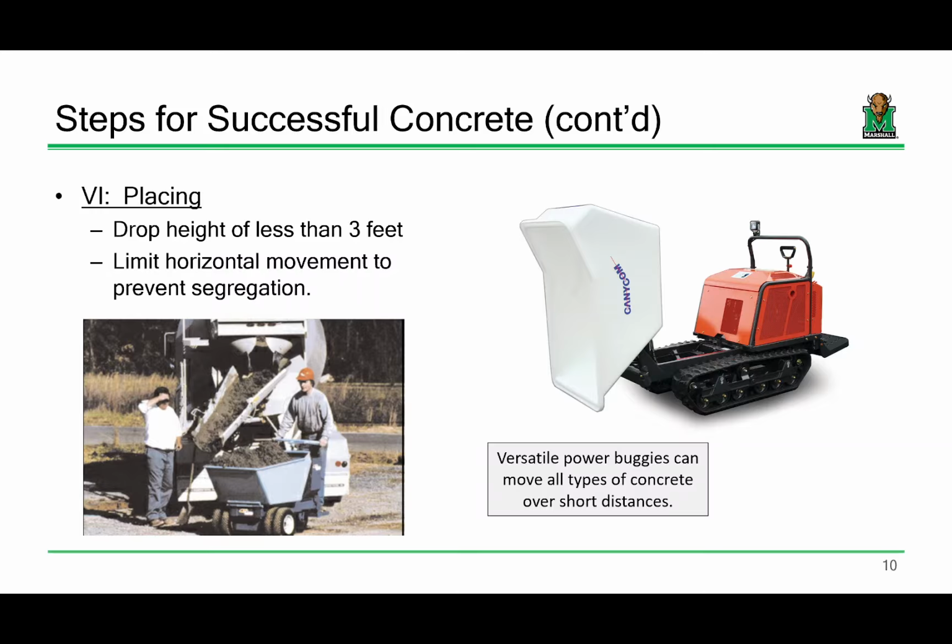Okay, so a couple things to keep in mind. At the time that you're placing it, it is a wet mixture of gravel, sand, cement, and water. So what you don't want to do is open the chute and just let it fall 20, 30 feet.